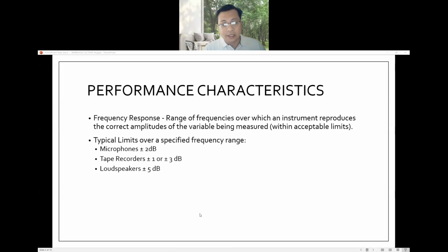Yeah. So after we collect data and sum the sources of noise, we can compare to the standard. The standard is already listed in a table, so we can check which category of building this is, refer to the table, and see whether it is still within the limit or not. Typically there is a limit for a specified frequency range.